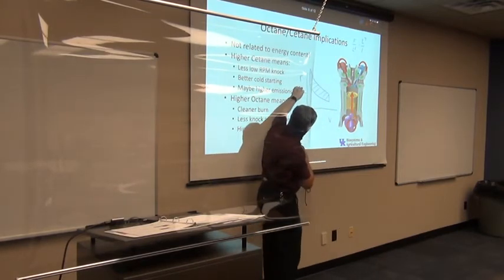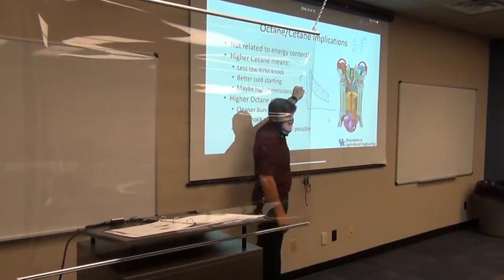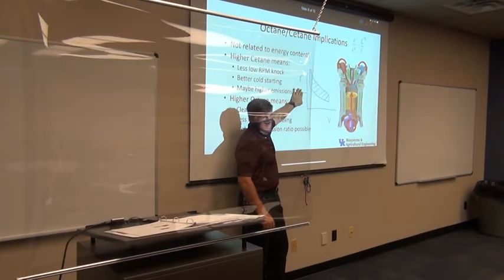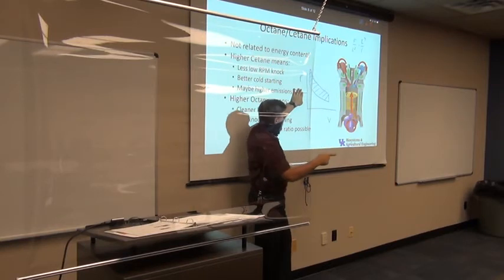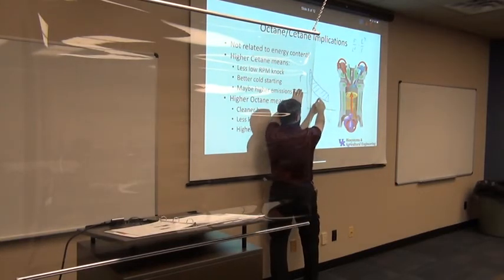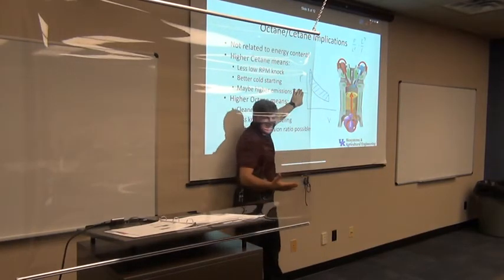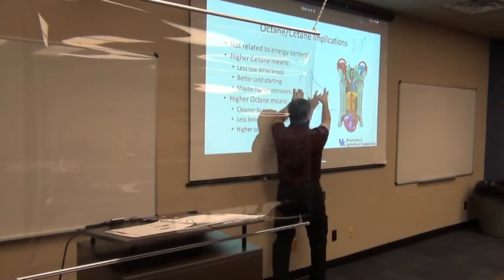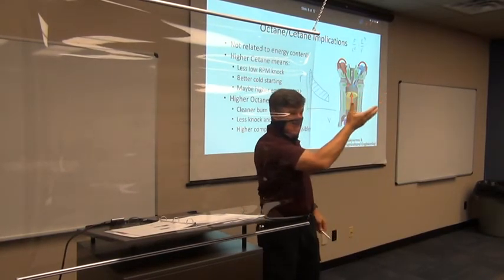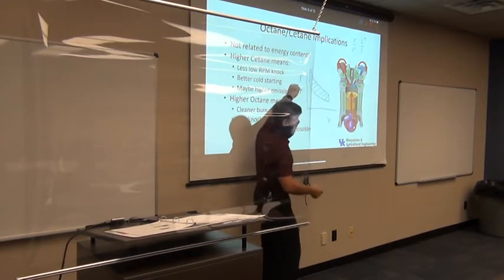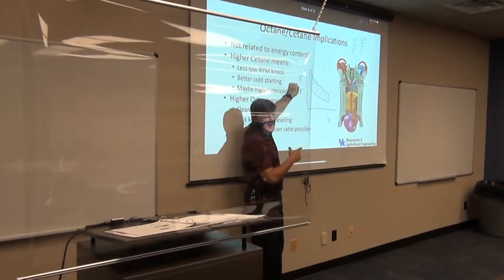What happens if the auto ignition pressure of the fuel is here? Let's say that it's right there. What's going to happen in that engine? It's going to ignite, sure, because the pressure in that cylinder at this point is going to pass the auto ignition pressure of the fuel. That's going to make the fuel ignite. That's not good because that piston's still going up. That's bad. So where does the auto ignition pressure of the fuel have to be if this is a spark ignition engine to make it work?